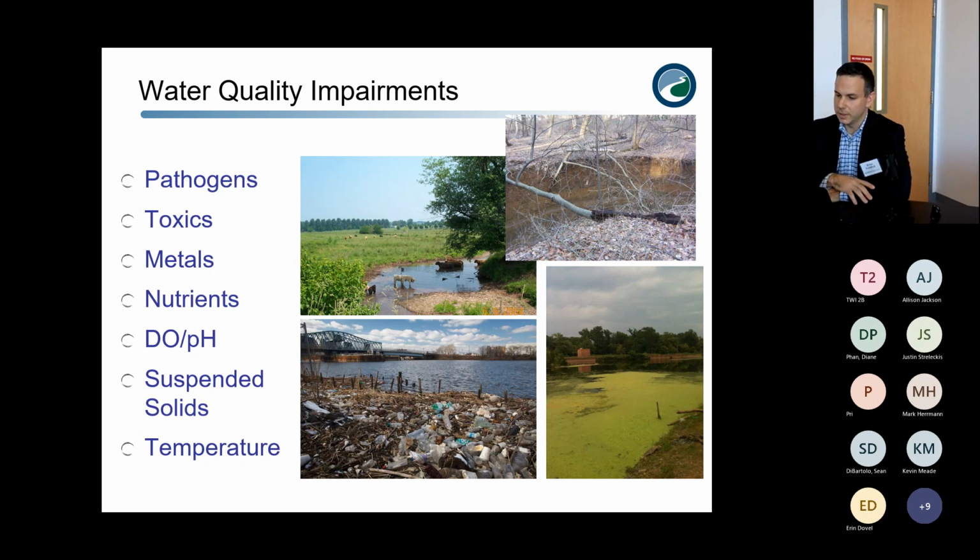And you could see the extensive erosion that occurred as a result of that, carrying with it TSS and pollutants downstream. And then on the bottom left is a site in the Passaic River where we have toxic issues, metals, trash, TSS. And so all these require implementing stormwater BMPs to address these water quality impairments.